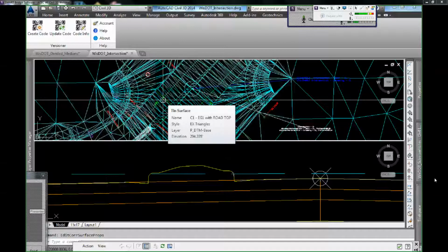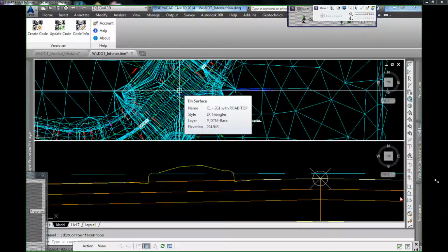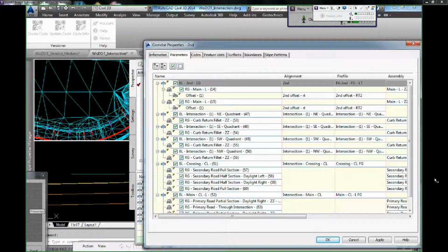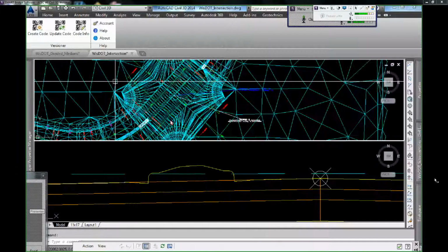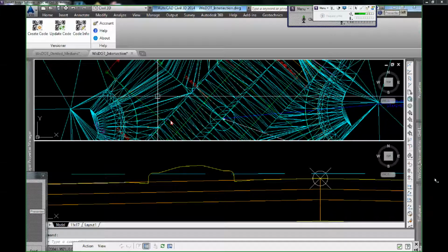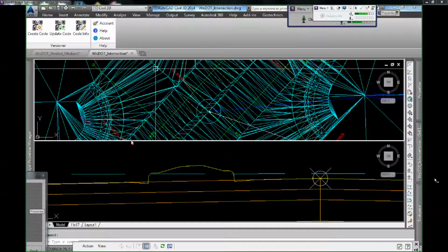Well, yeah, what we would rather see is use all those additional corridor feature lines to define the surface rather than the links. Yeah, but the problem is you need some way to connect these lines in this direction. Right now you're running feature lines along this line, along this line, along that line.